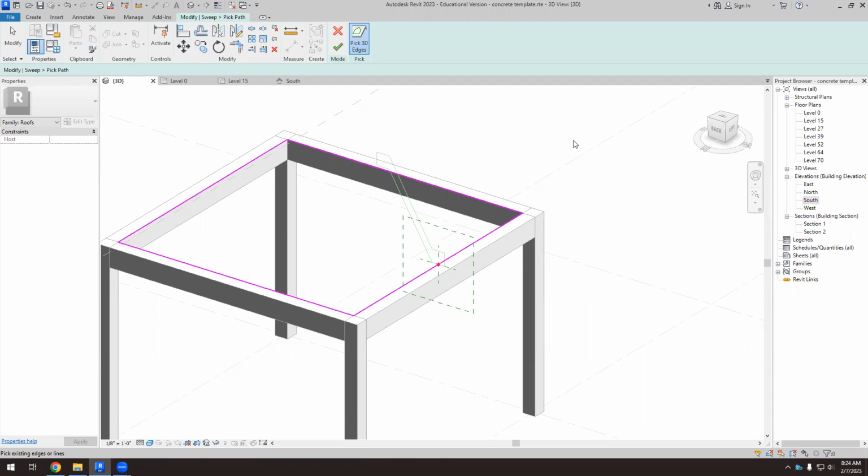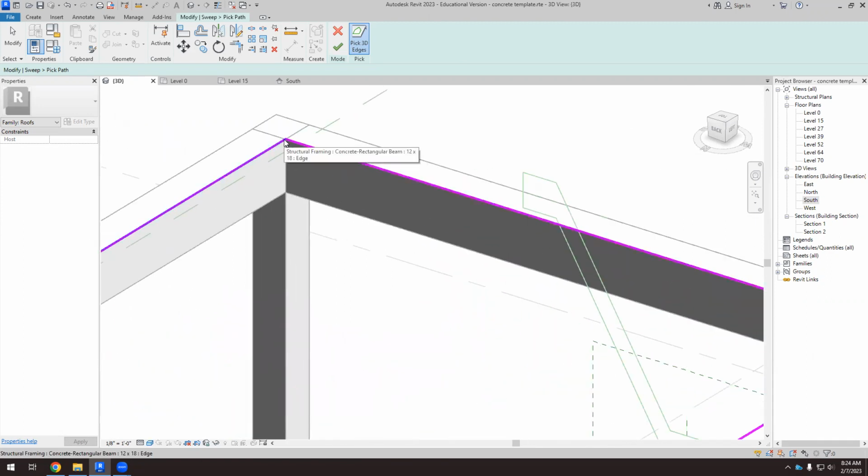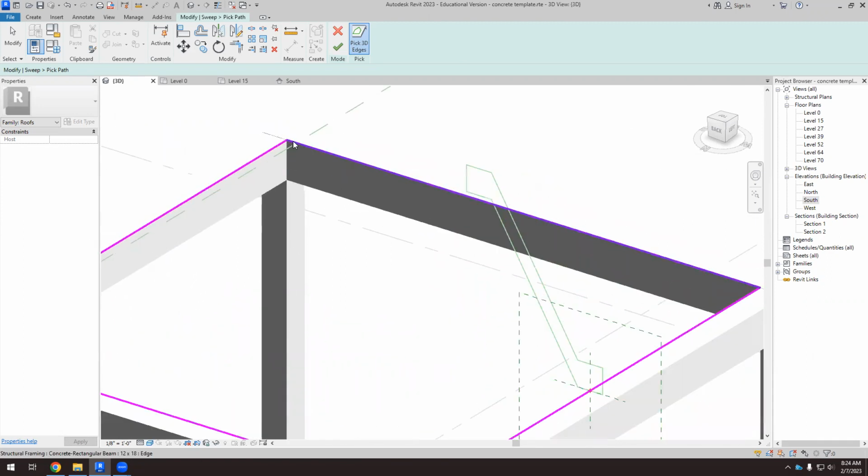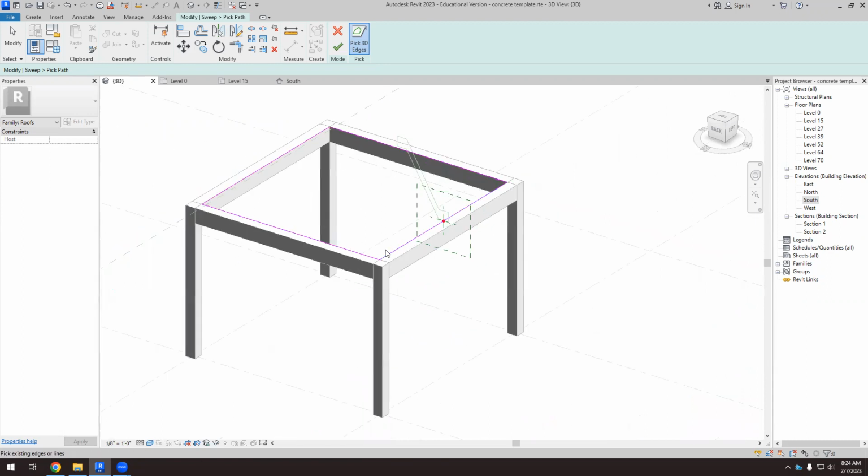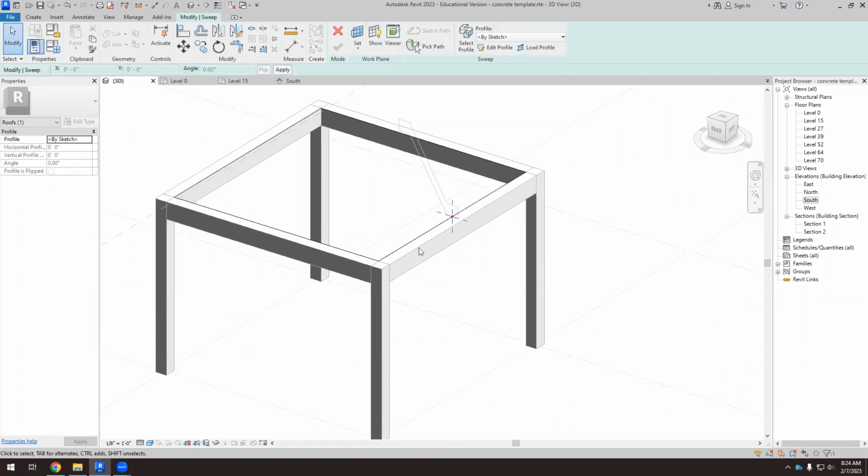We need to select then the shape, and then with this point, we will move that shape around these big lines, and then we will have this solid, I hope. Okay, so once we have selected the path, and again, it has to be closed. If it's not a closed loop, it won't work. So I think they are all, it's a closed loop, so we can do this.